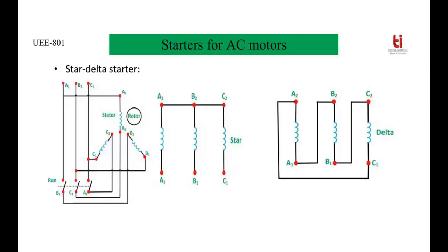Star delta starter. Here the problem of the direct online starter is reduced up to some extent. We know that if we can reduce the supply voltage, then the current will reduce. So that technique is used here.